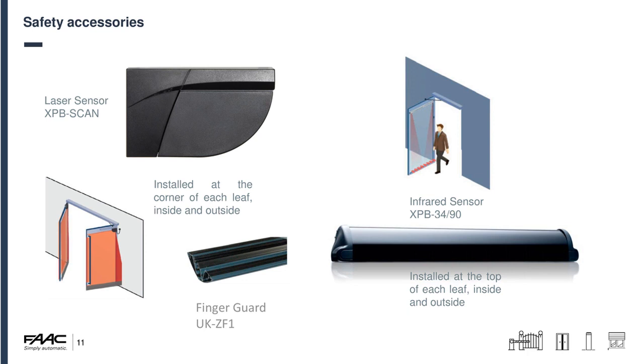Safety devices are basically, you'll see where our XPB is. These fit on the external and the internal side of the face of the door. If the door is over 900mm, we would suggest the internal one being a double modular safety sensor to make sure it covers the whole closing application of the door. The 340 sensor goes on the external side, on the opening side, and your finger guard would be put on this if it was an open hinge.